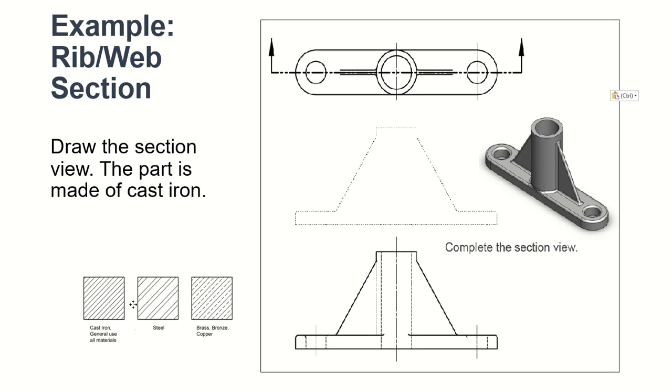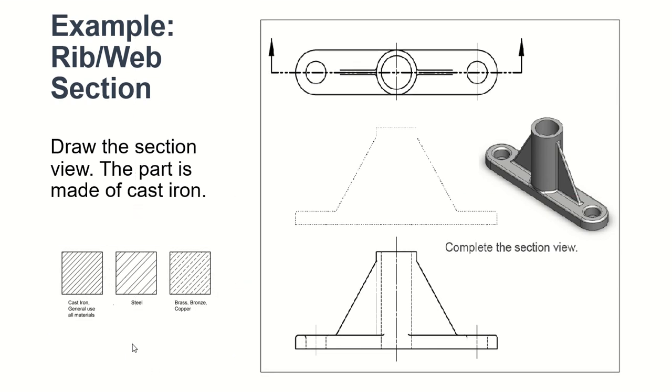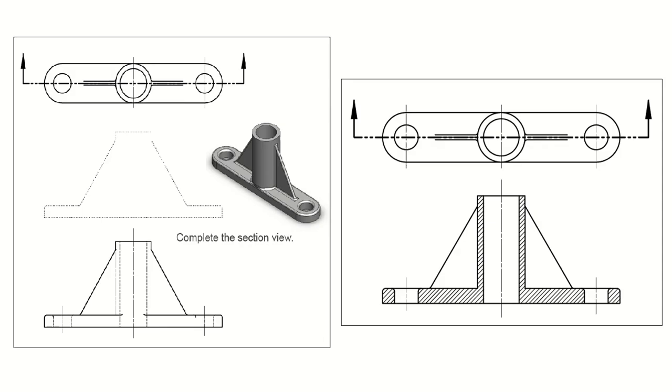So you bring in this thing again. I've been copy and paste. So your cast iron is this pattern, and we're gonna be cutting this way, keeping that, and we're gonna look at it. Don't forget to turn it, not just looking at it, but cut it down and turn it, so you will see inside, yeah, structure.